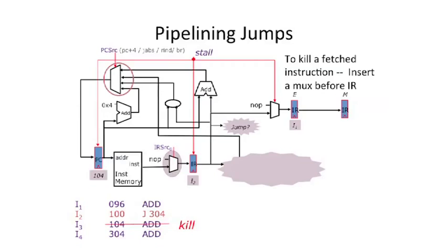And this is what I was talking about before about the extra adder here. Here's our extra adder, which is computing our destination. Sometimes people try to put these two things together, but we're going to take part of the instruction, and we're going to take the current PC and add to that, and that's going to compute our new destination of the jump. So here's the control on this mux. We just have to look to see if it's a jump or jump and link, and then we insert a no-op. Otherwise, we actually take the thing coming out of the instruction memory.